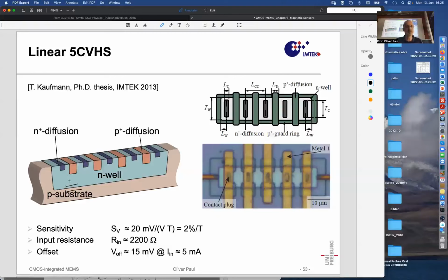It is definitely better to be in the lower doped region, because the Hall mobility is higher, so you can theoretically get better sensitivities, because for instance, the voltage related sensitivity is proportional to mu.